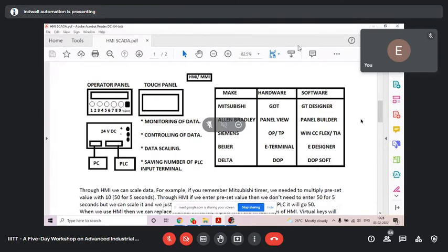Data scaling. What is this? I shall tell you. One guy had asked, why did we divide percentage MW1 by 1000 in Codesys visualization? You remember, no? That timer meter display or digital display, we had taken percentage MW1 divided by 1000. An answer had also come. I don't remember the name of the guy, but he had answered that also. That was correct. But everyone, I think, did not understand. See, there we did data scaling actually.